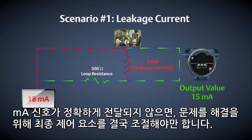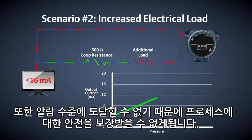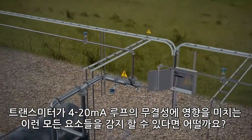If the milliamp signal is not being conveyed accurately, you may be making adjustments to final control elements that are not required, causing bigger problems. You also may not be able to bring your process to a safe state because you're unable to reach alarm levels. What if your transmitter could detect all of these changes that could impact the integrity of the 4 to 20 milliamp loop?